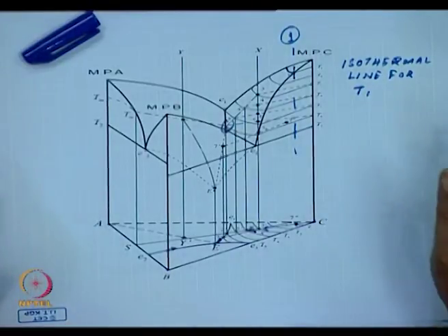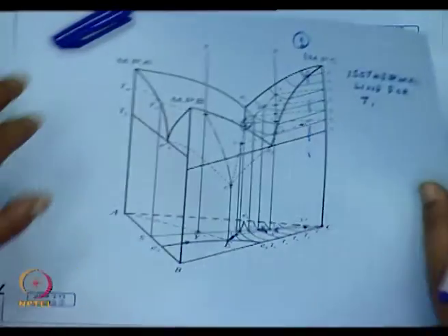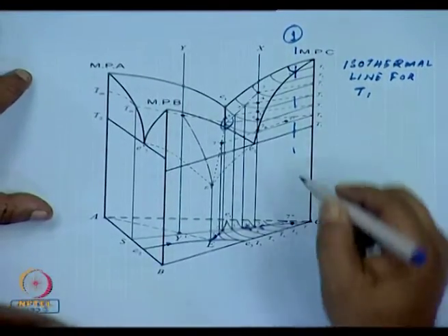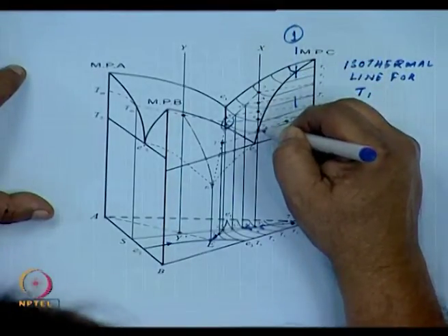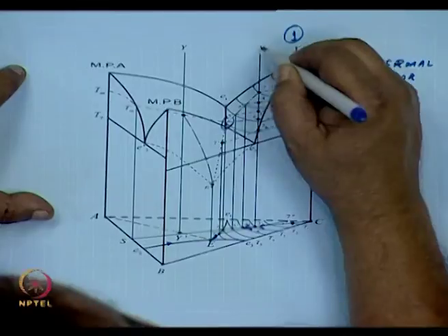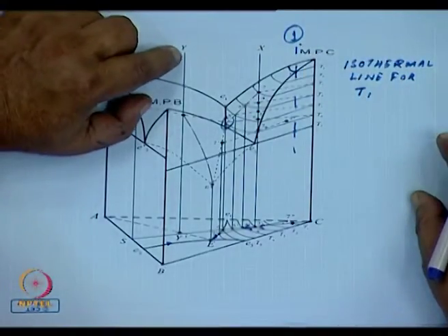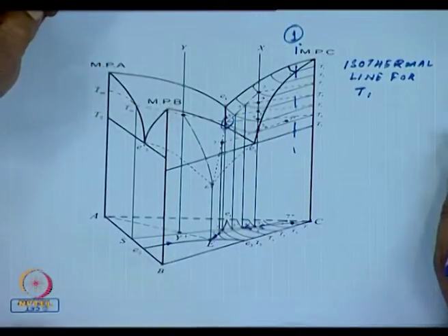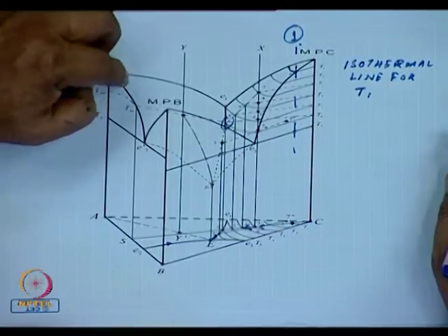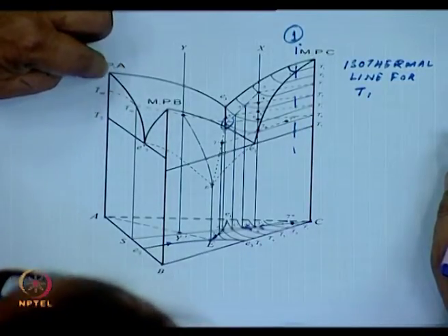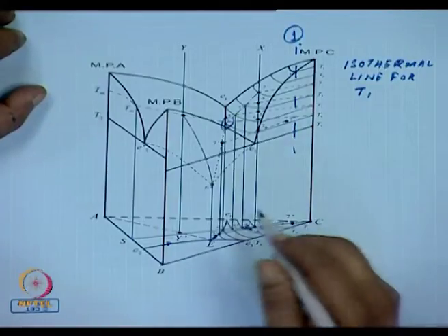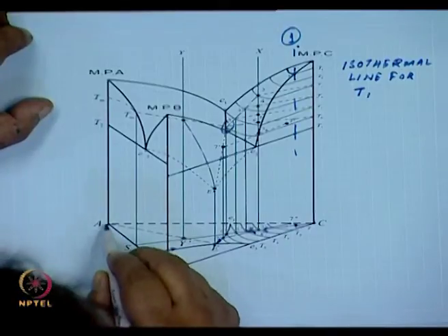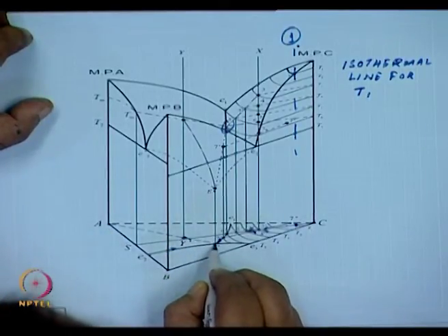So here what we get essentially, if I start off from that, is the cooling path of any composition X. It can be here or here. For example, there is a Y over here. I have deliberately drawn it. Obviously, you can see this Y is hitting this A1E. So what happens with the Y is the cooling path will then be following in this particular way.